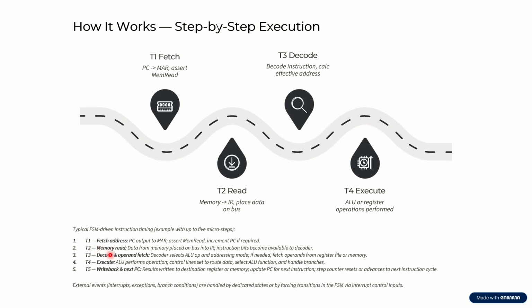The next, T2, memory read: data from memory is placed on the bus into the IR, and instruction bits become available to the decoder. Then decode and operand fetch.